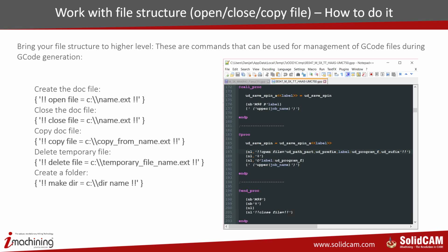And the second example is in very high-level mill-turn machines, where you have 2 or more channels. Whenever I say channel, that means this machine in most cases requires 2, 3, or whatever number of channels you have, Gcode files. So separate Gcode files for each channel.